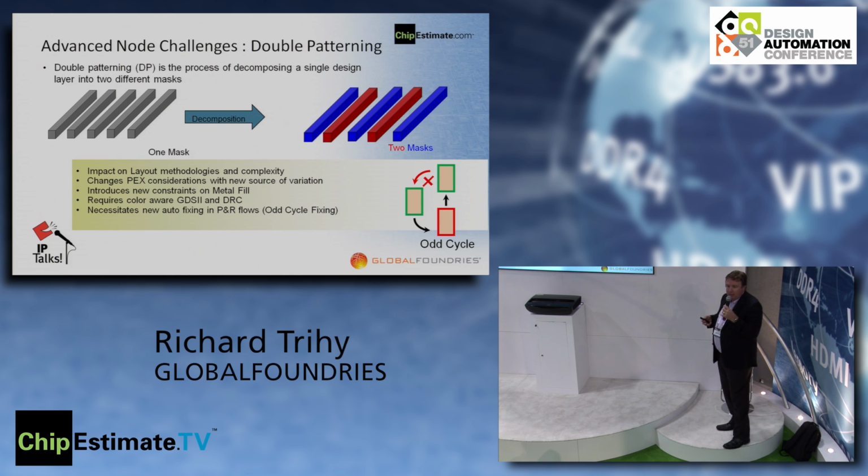There are also new constraints on metal fill. Historically, we've looked at fill as something where we had to achieve a certain density. Now we also have to achieve a certain color balance with the fill. It requires color-aware GDS2 and DRC, and in the place and route flows we also see significant enhancements, where we require odd cycle fixing to be built into the place and route flow. And this is a must-have to be successful at 20 nanometer.